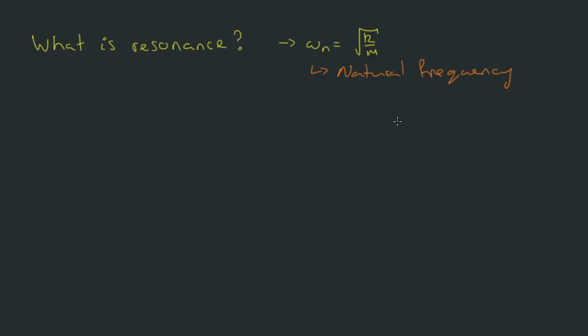So we want to know what our natural frequency is, and you can see that we can't really vary our natural frequency after the design stage. For example, this k denotes our stiffness in a system and the m denotes our mass in a system. So once we've designed and made something, it has a stiffness that's set. It has a mass that's set.